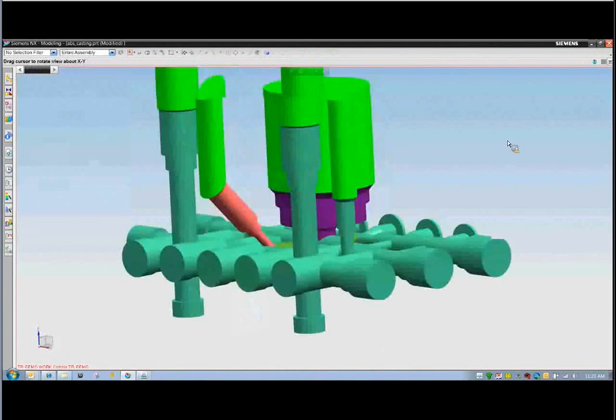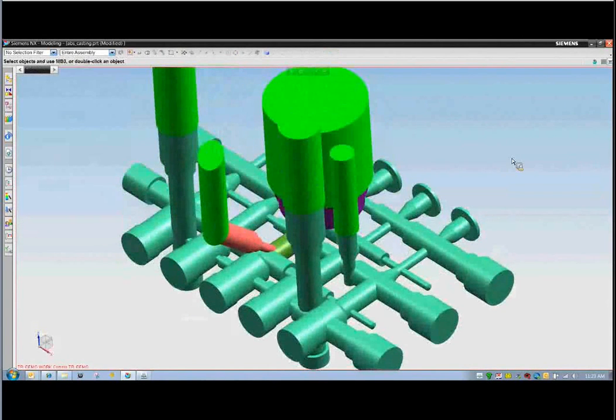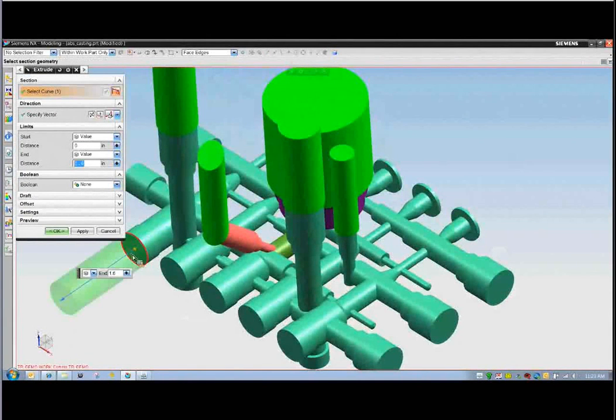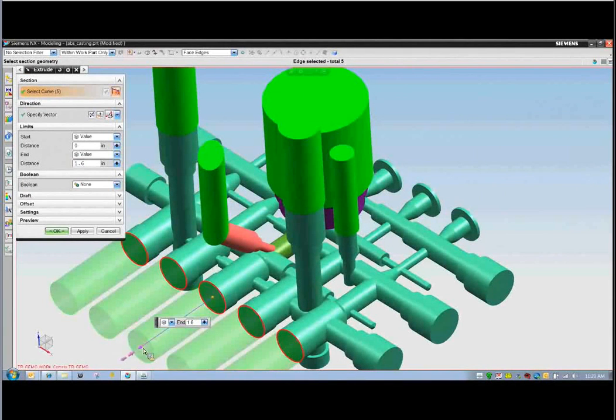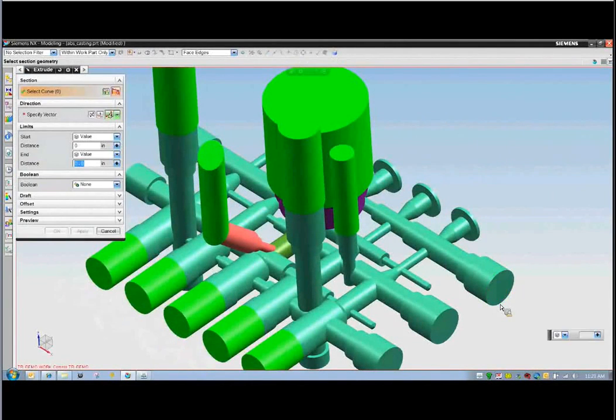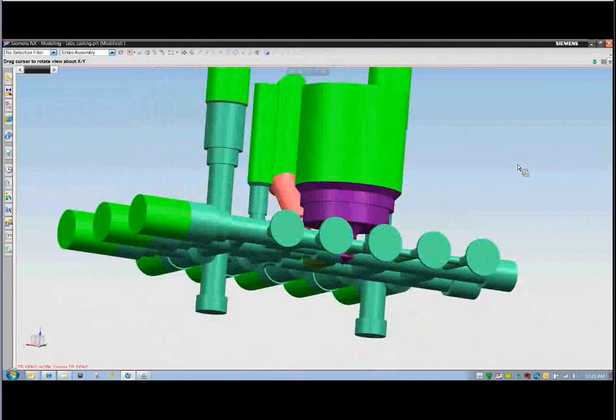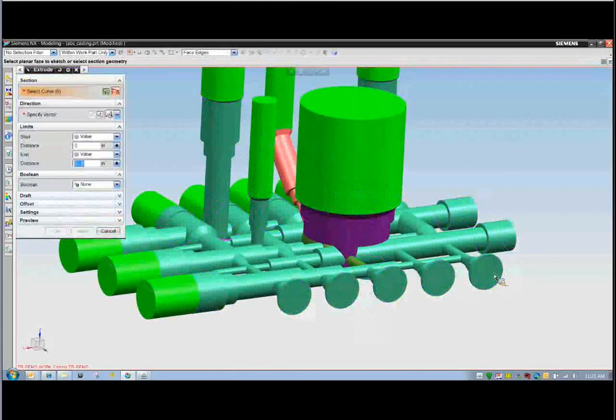We'll accept that. So there's the core prints going in that direction. If I select X, it allows me to do core prints in another direction. I'll shorten those up a bit. X again for core prints going in this direction. So we'll just walk through all of these.